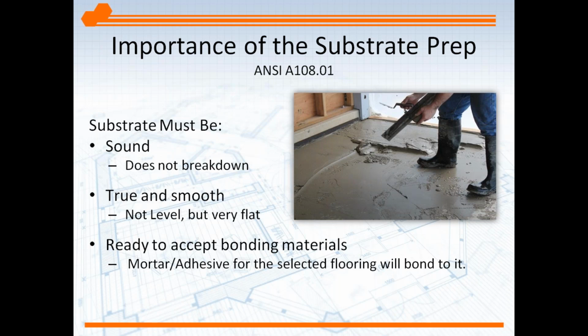This is extremely important because the mortar does do exactly that. Cement-based mortars, Portland cement-based mortars, they'll bond to a concrete substrate with adhesion, absolutely, but also by growing into that concrete a bit, providing a mechanical bond. So those concrete substrates in particular need to be ready to accept that bonding material, meaning they need to be porous enough for the mortar to grow in, but not too porous.